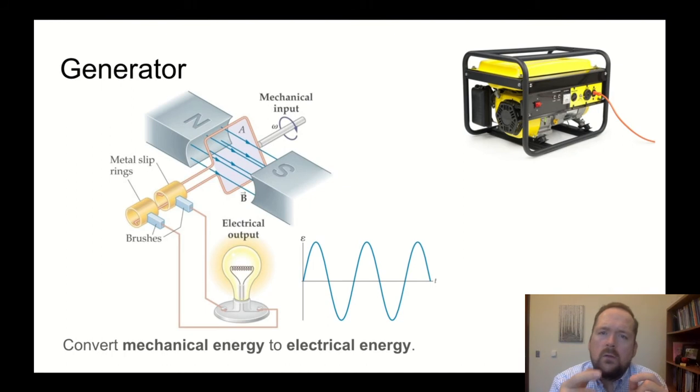And we choose the alternating current in our electrical grid systems to be such that it's switching back and forth rapidly enough that it's not like the light is blinking on and then blinking off all of the time. It heats up and it glows, and by the time it would have cooled off and stopped glowing, the current is in the other direction. So you just see steady light out of a light bulb, even though the current is actually switching directions 60 times every second in a US circuit. So that's a brief touch on generators.